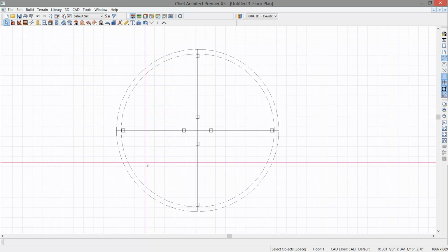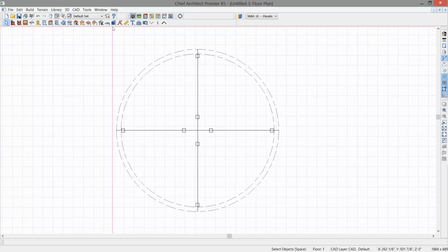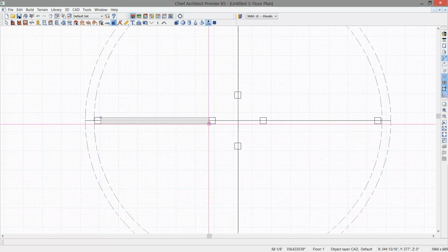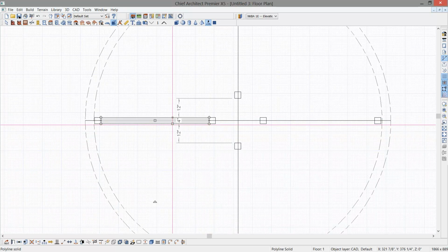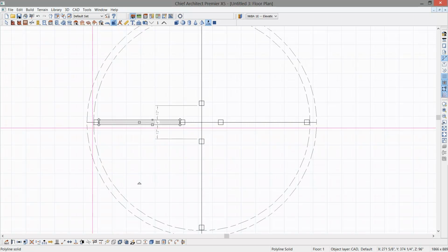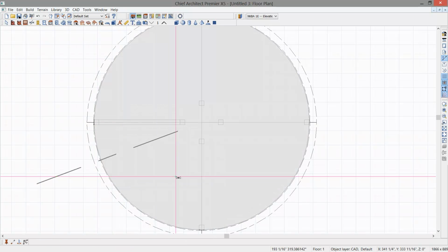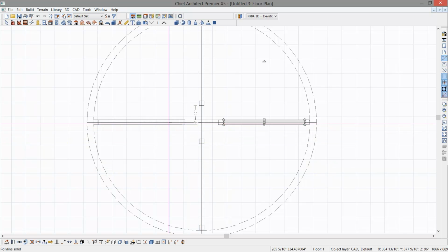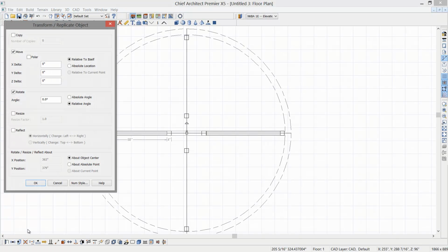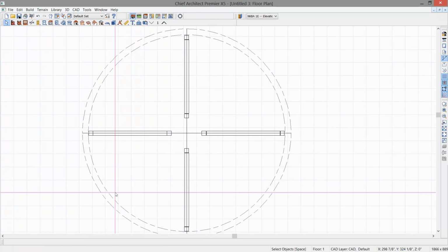And now let's go ahead and use the same slab tool. And I'll show you a 3D view here in just a second what I've got. Use the slab tool, and let's create another slab in here that'll be used for the sign panel. Open this one up. And again, the elevation at the top, 96 inches, 54 inches for the total height or thickness of it. Select OK on that. Copy, reflect about the center. Flip that one over and grab both of those, and we'll use the Transform Replicate again. And a copy and 90-degree angle. Select OK, and now I've got that.